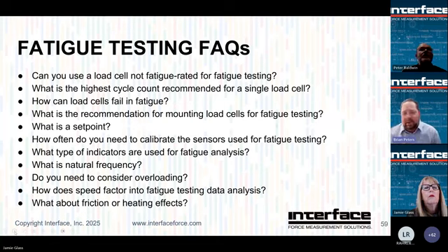You don't want to have that cable zip tied up to maybe something up on the other side of your test article, right? Because now you've introduced a parasitic load path outside of that bridge, where now you've got not just the thing attached to the live end of the load cell, but now you've got this cable that's also influencing around the bridge. Hopefully that helped.